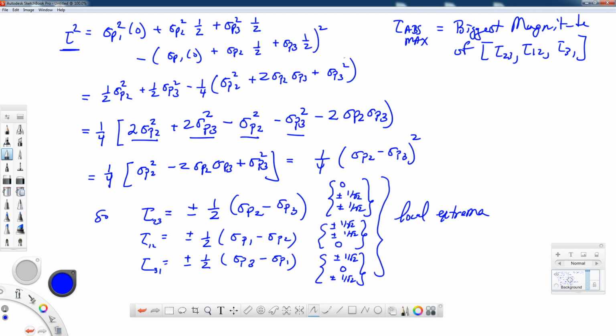Now one thing that we can't necessarily do with these equations is tell you if the shearing stress is pointing towards you or away from you. But we can figure that out if we look at the problem more physically, or through the perspective of a Mohr circle.